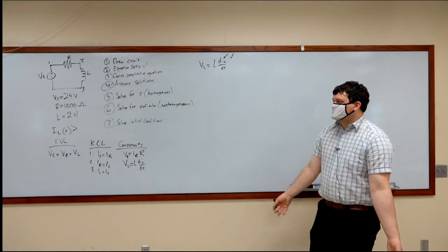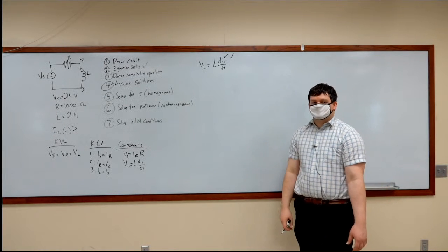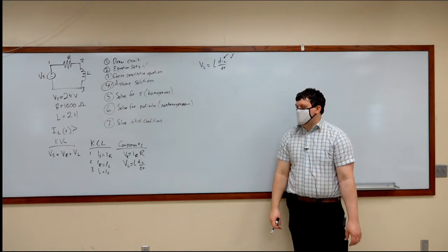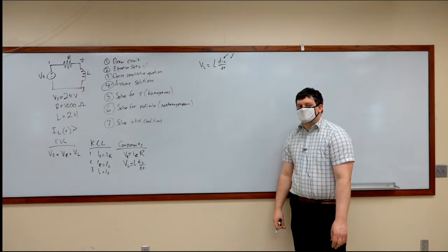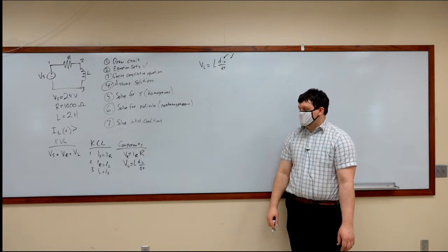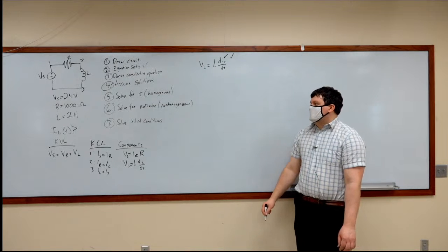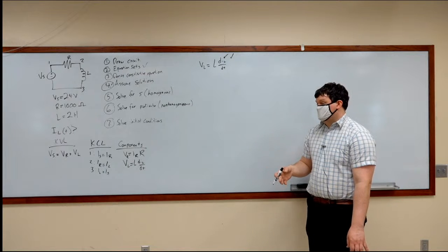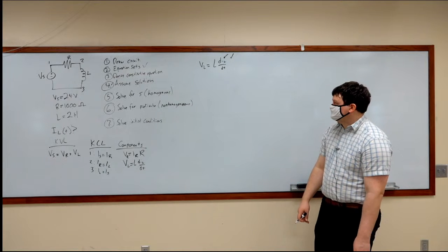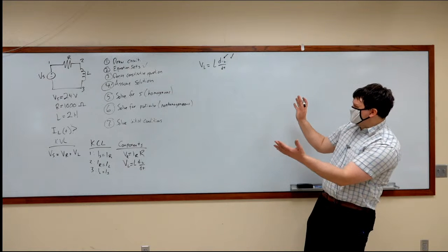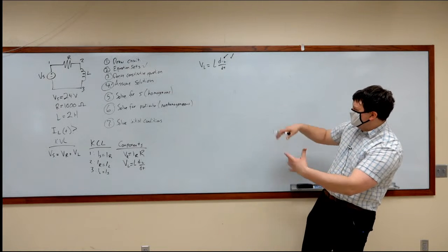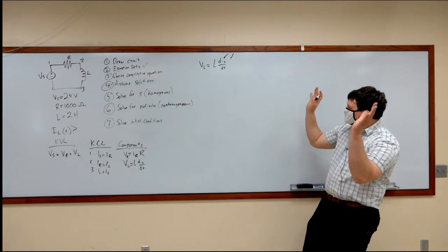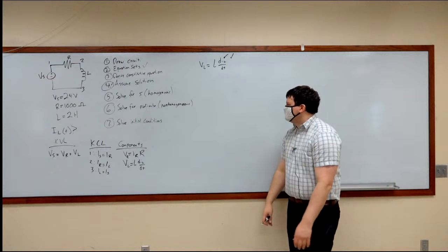We want to get it equal to a forcing function. Okay? What is our forcing function for this system? What ultimately is powering this system? It's Vs. So we know our final constitutive equation is going to have some function of Vs in it. So that's good. So we need to somehow get Vs in here, lose the VL, and gain another IL somewhere with magic.